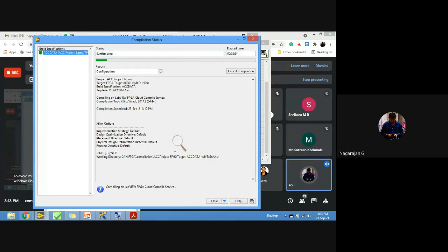If you want to send any audio command as an output, it is sent from RT to FPGA, and then we get the output. The audio output will be in terms of fixed-point numbers, so we have to go for the data conversion: LSB weight times the raw data is equal to the voltage. We need to take that.